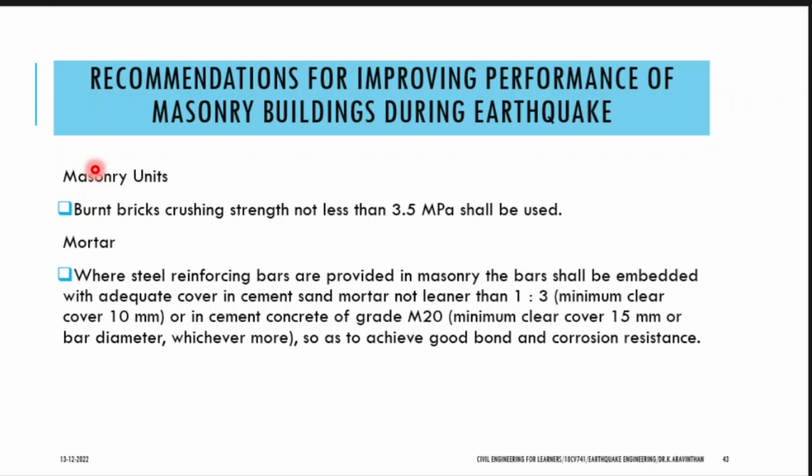If you check the compressive strength of a brick, it might be 2.5, 1.5 Newton per mm square, and 3.5 Newton per mm square of strength is also available in the market. You should use that for construction.